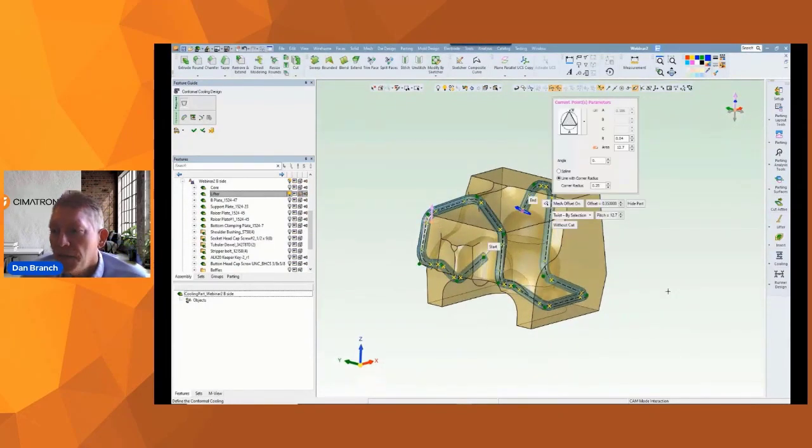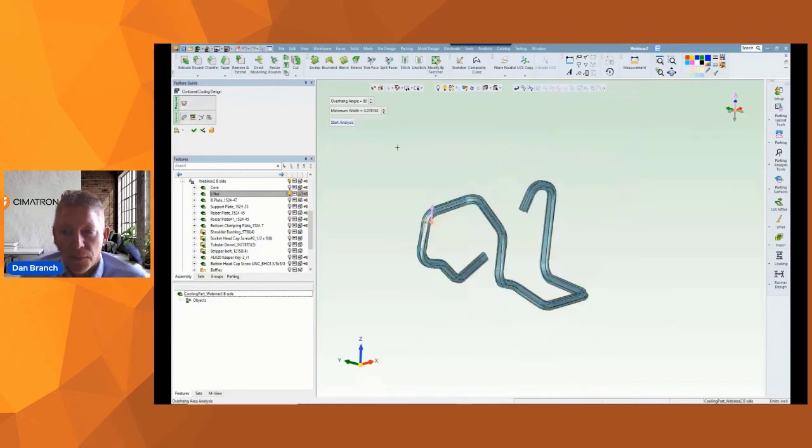And I can have the same function, while I'm designing, do some analysis on the channel. One of the checks I can run is an overhang analysis. I mentioned downward facing surfaces are not good, but as we can kind of assume, they're unavoidable. So what this does is it measures the ramp up to those downward faces. The printing machines can make the next layer of material okay if the angle is slight enough. So here the triangle section is a good one to use, and I don't see any problem at 45 degrees. But if I change that ramp up angle to 60 degrees, then I do get some yellow areas, and those would not satisfy the condition. So maybe I make some adjustments to the channel or to the twist.